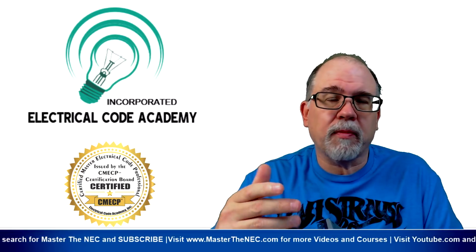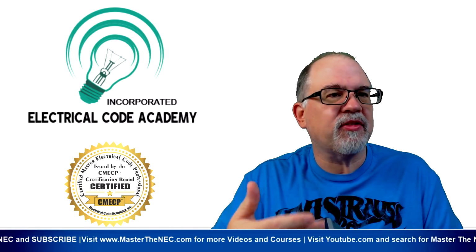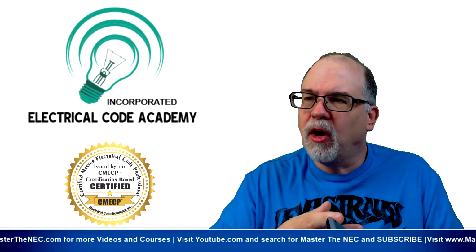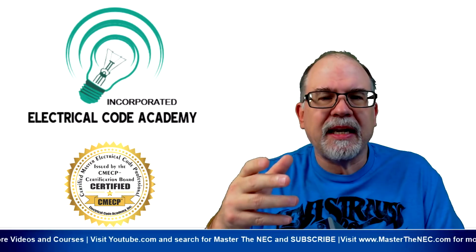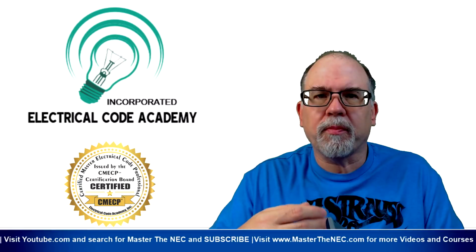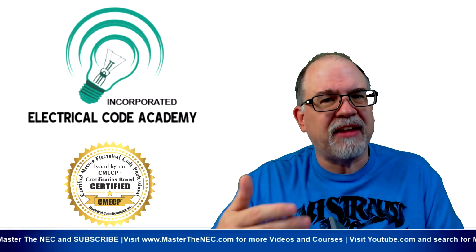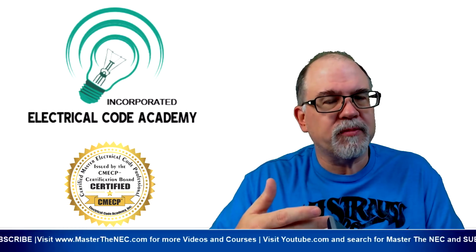Pretty simple things to remember, but if you're taking an exam, that can be beneficial to you, because on an exam, you need to know in many cases how to calculate the primary current rating of that transformer or the secondary current rating of that transformer, because everything else builds off of that. The overcurrent protection for the primary winding or the secondary winding is really based on that transformer's primary or secondary current rating. And you have to be able to do that calculation. So it's important to remember how you do that if you have an exam and it asks you a question about the overcurrent device for the primary or secondary protection.